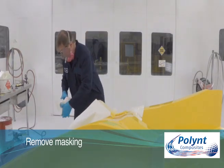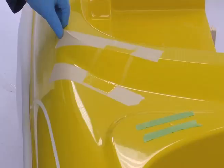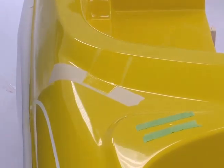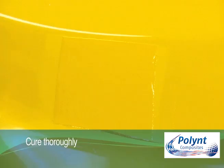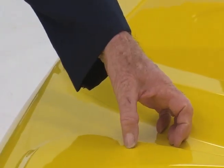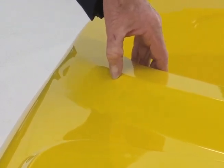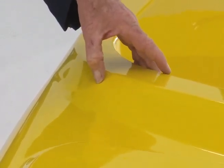Remove all tape and masking material from the patching area. Keep any masking used to protect areas outside of the patch area until all sanding has been completed. Allow the patch to cure thoroughly. If time allows, let the patch cure overnight. The patch is not cured sufficiently if a thumbnail leaves an impression on the gel coat.